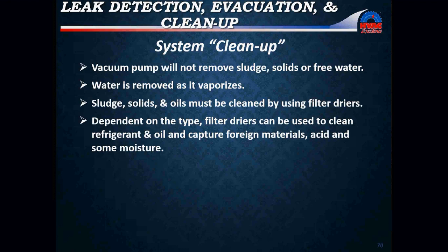So when the compressor motor burns out, for some reason, the high temperature arc causes the refrigerant oil mixture to break down into sludge, acid, and water. If the contamination from the burnout or the sludge reaches the replacement compressor crankcase, the replacement compressor will probably burn out.